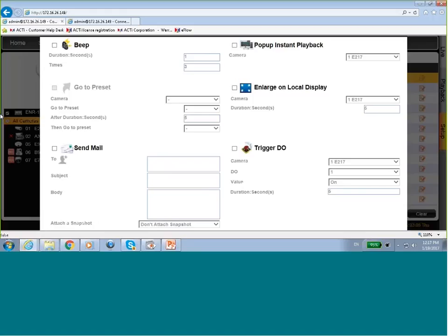Yes, this is useful and more powerful than motion detection, because with motion detection, we all know there were so many false alarms before. But with video analysis, it can be more precise. For example, line crossing: if there are pixel changes crossing the line, it will trigger the alarm. So the focus is that there is one application that's widely used for fisheye cameras, because fisheye cameras can cover a wide view, either 180 or 360, to cover the whole area.